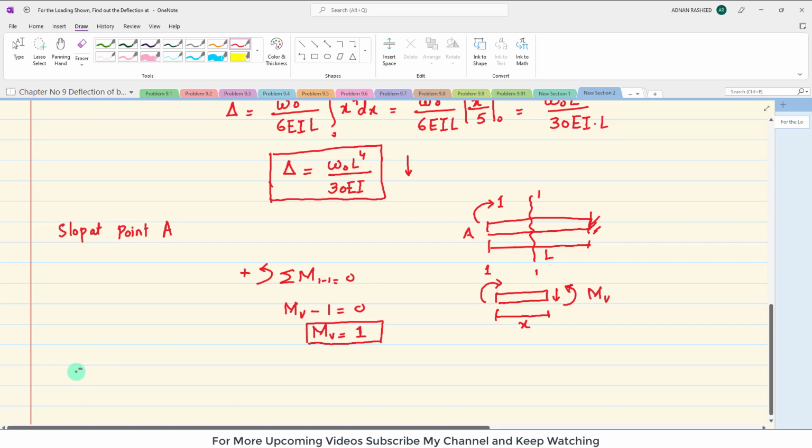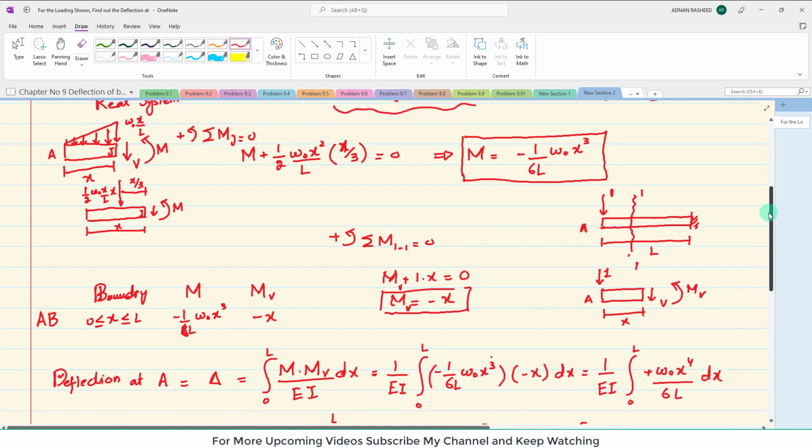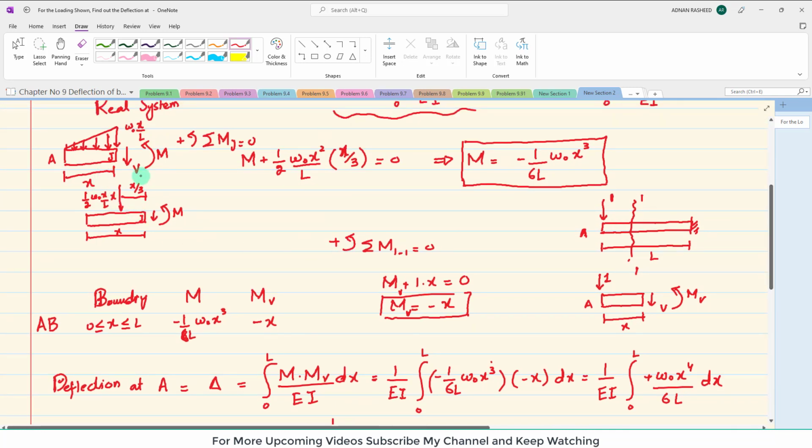Now, for finding the slope at point A, you have integral of 0 to L of M into MV divided by EI into dx. So again you have to put the values. 1 over EI is taken out as these are constant, so 1 over EI integral of 0 to L, and M is again the same because this real moment will be the same.